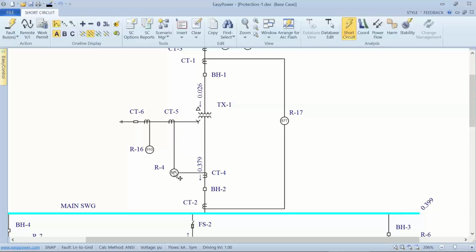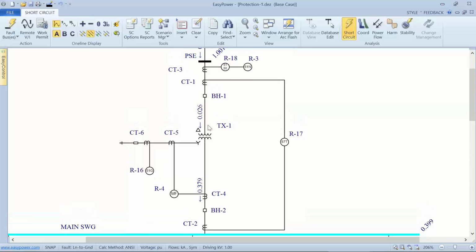So we can use that as the maximum point for our ground fault protection, or at least to scale our CTs and our current, knowing it will never exceed that particular number on a through fault, or on a fault, period. Now on a through fault, the maximum current that we'll see on the primary side is 26 amps. And so when we're talking about fault protection for R3 up here, we can actually use an instantaneous setting because this will be the maximum current on a through fault. Anything beyond that, we could assume to be an internal fault or a fault upstream of the transformer.